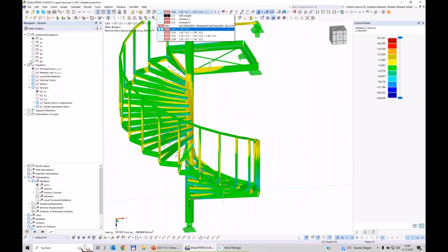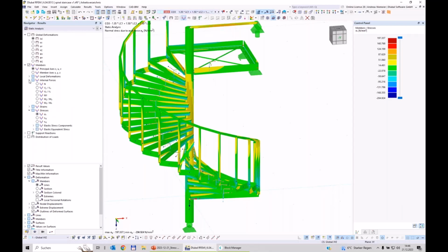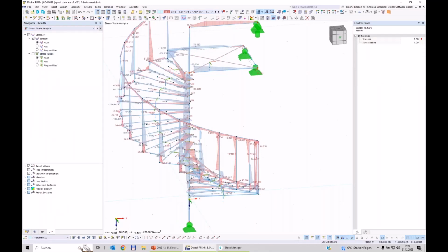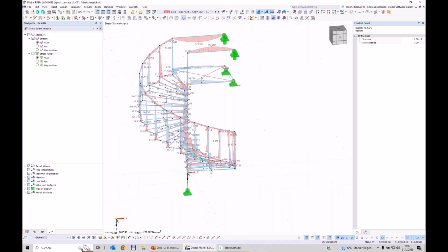So therefore, we are always interested in this stress check, which makes an envelope of everything. Of course, drawing a multicolor picture on the cross section is difficult, but we visualize it then with such a diagram. So the program detects, and the most important information here on the bottom, we have a maximum stress of 203 megapascal.